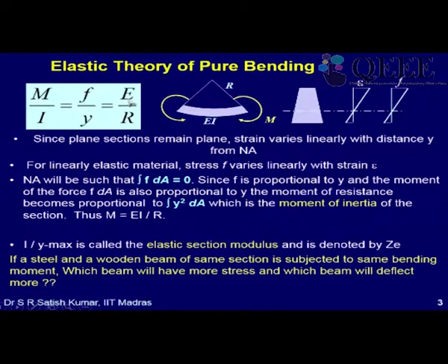Whereas in steel beams the E values are very high. So what happens is you don't really see the deflections. Okay, so you know that it has deflected, but normally under small bending moment you can't see the beam deflecting appreciably. Okay, so that is one.